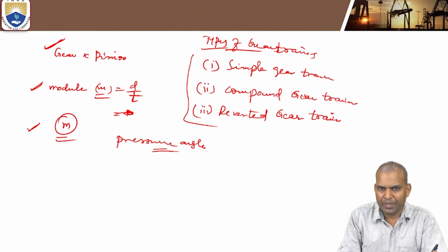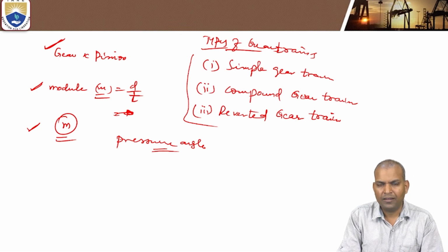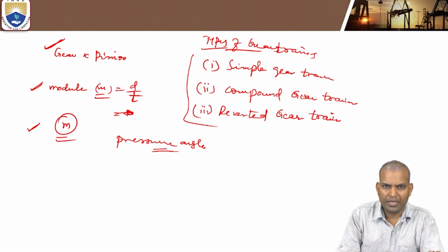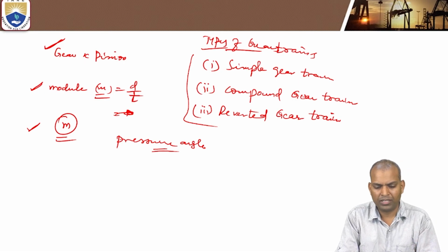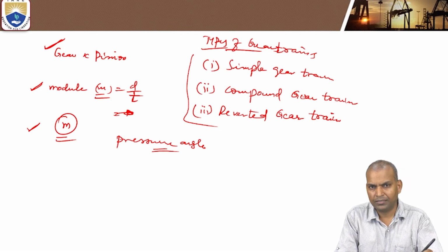Now, the contact between two teeth is either point contact or line contact. According to the concepts of kinematics of machines, two gears mean one pair, and this pair contact comes under the category of higher pairs. For higher pairs, the coefficient of friction is low in comparison to lower pairs. For lower pairs the friction is very high, so less power is transmitted. With higher pairs we can transmit more torque. That's why we use them here.